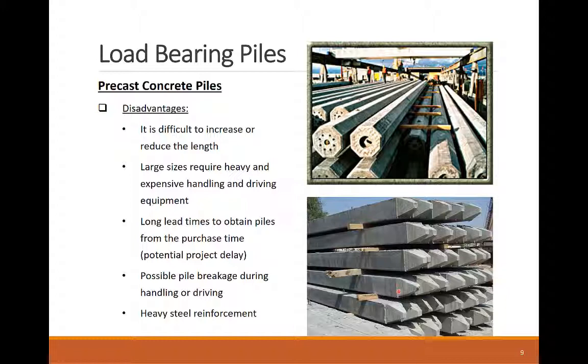Finally, precast piles are vulnerable to damage during handling, especially if they are a long cylinder. So to overcome this problem, additional reinforcement is included in the pile design to account for the pile load in case of handling and rigging it.